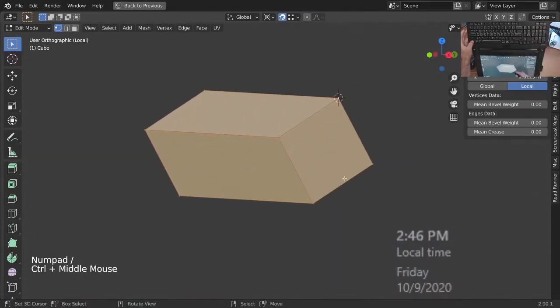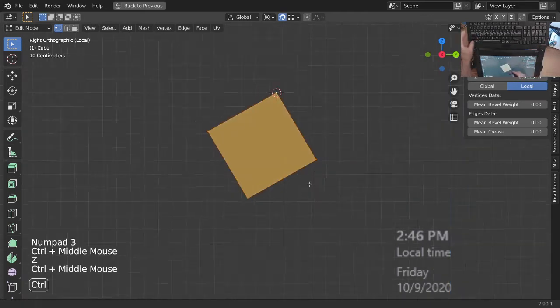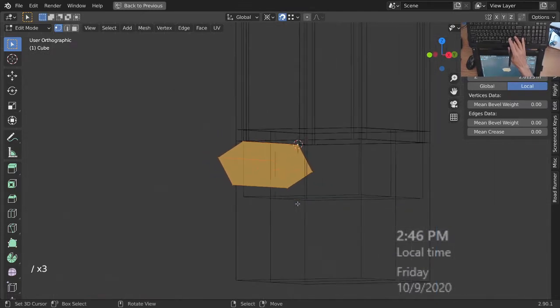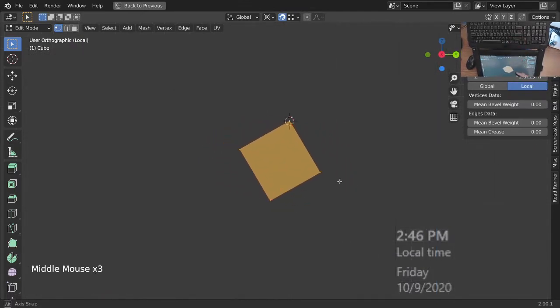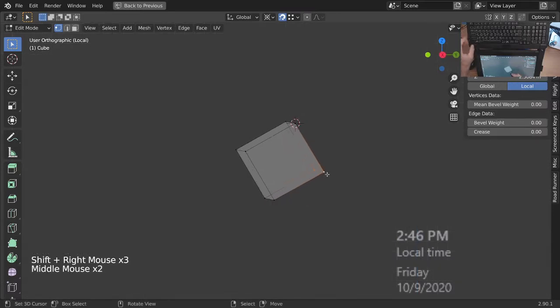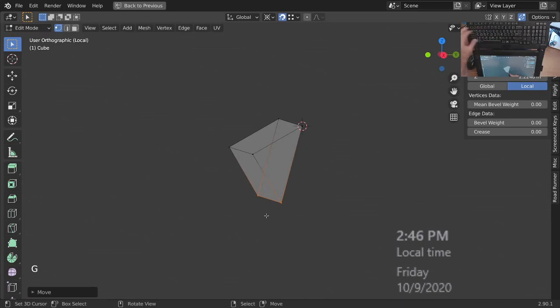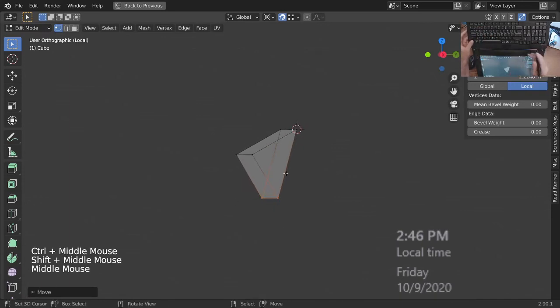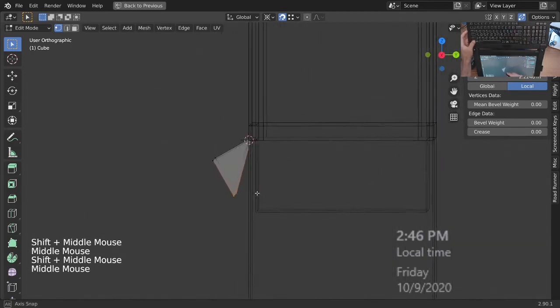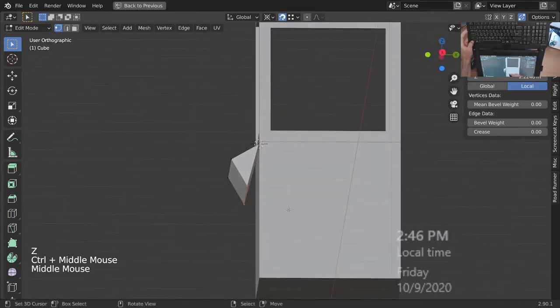I'm going to hit the slash so I can just work with this one. I'm going to go to the side view, and that was the slash on the number pad, and I think the slash on the keyboard works as well. So there, I'm doing that slash on the keyboard. On the side view, I'm going to select those, and then turn on the welding, the little merge button there for the vertices. So when I do a function like this, it automatically merges them. And now I'm going to come back out of the local view and just look at it like this.